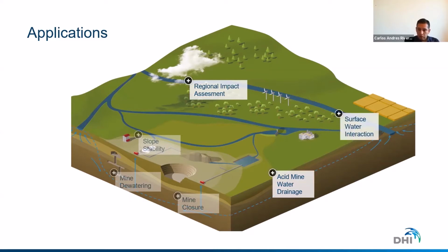We have a couple of options you can use to model surface water and groundwater interaction. So either you simulate this from FEFLOW by prescribing the information directly to a boundary condition, or we have developed over time different specialized solutions. I will talk about the so-called IFM lakes, able to simulate lakes and interaction with groundwater, but we also have more sophisticated technology where you solve the surface water calculations hydrodynamically and provide this information to the software FEFLOW.